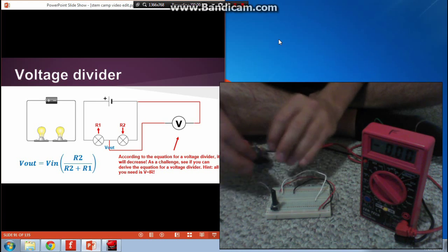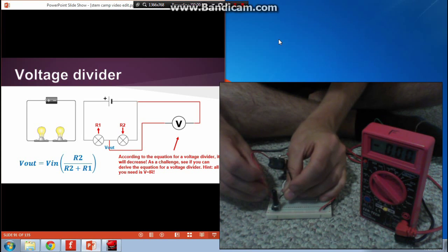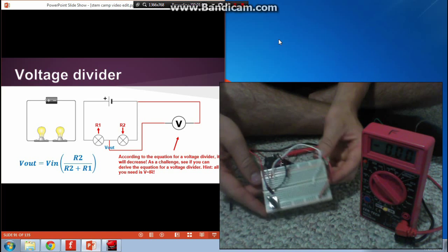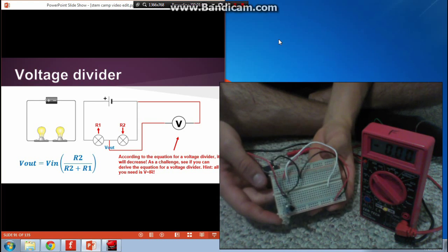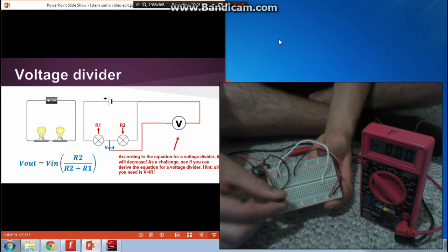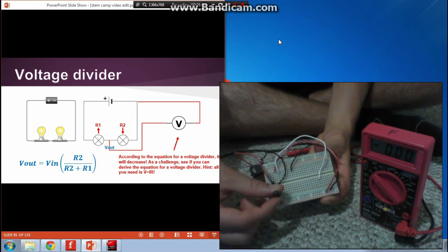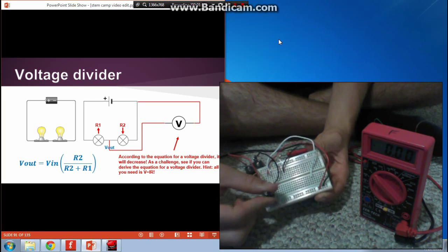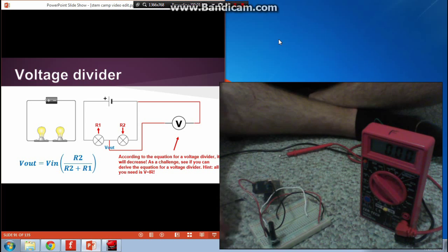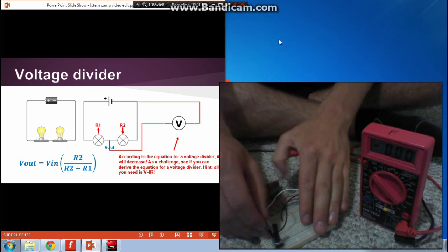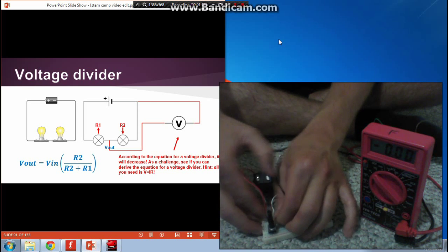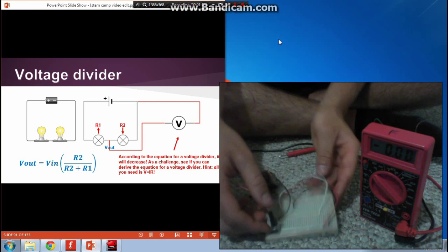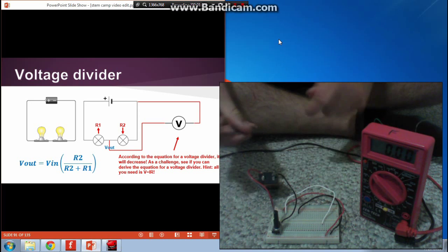And so now I'm going to plug this into a potentiometer. And a potentiometer is a voltage divider that you can change the resistances of by turning a knob. You should all have one of these in your packet, and I encourage you to try this circuit out too. You literally just follow the circuit that we drew up on the previous slides. Just hook that up in your breadboard, and if you need to cut off these little metal tags, you can have a mentor help you cut those off with a pair of snippers.